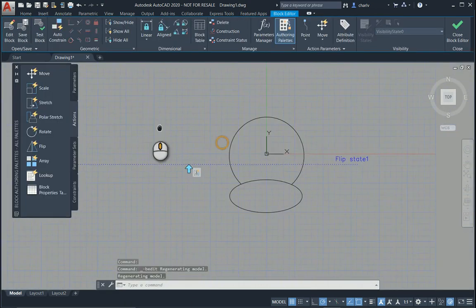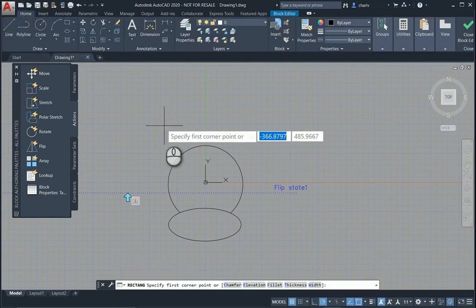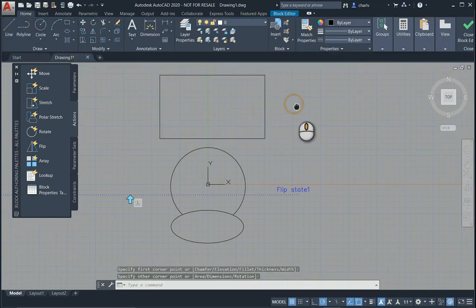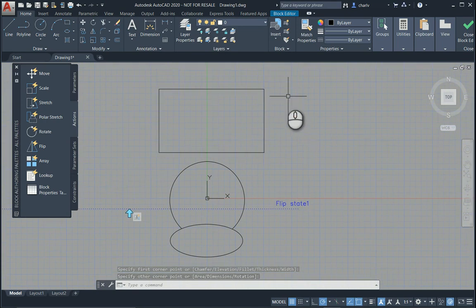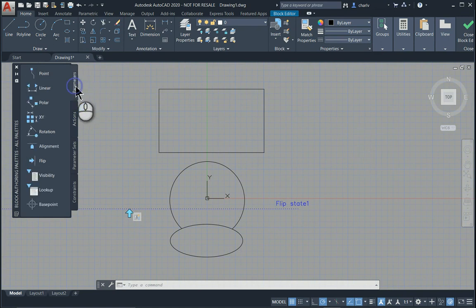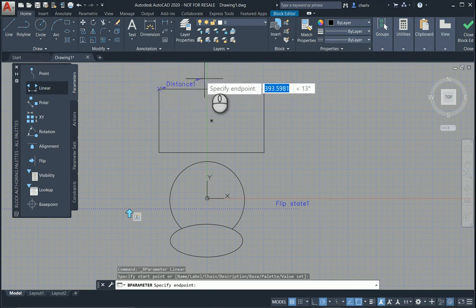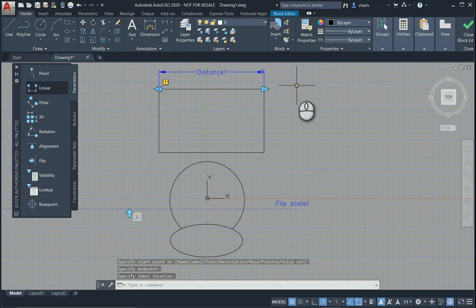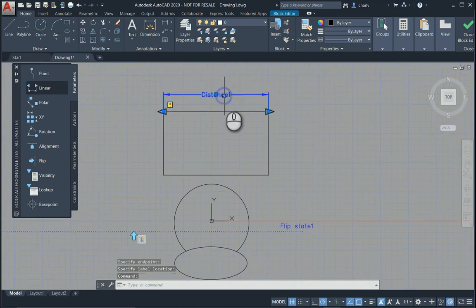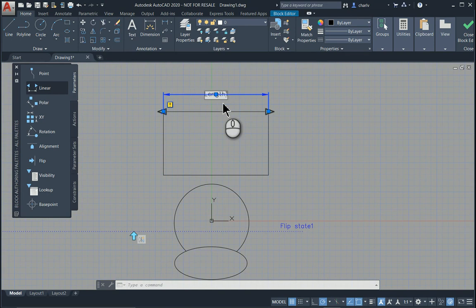Right, okay, so now perhaps we can draw up maybe a desk over here that the chair faces, and I'm going to want to just increase the length of this desk to the right, and in that manner show you how another parameter works. Okay, so I'm going to go to the parameters. I'm going to add a linear parameter, and I'm going to say, alright, we now place this linear parameter like so, and we could actually just rename this parameter by right clicking on it, and we'll say, for instance, length. I guess that's fine, length.